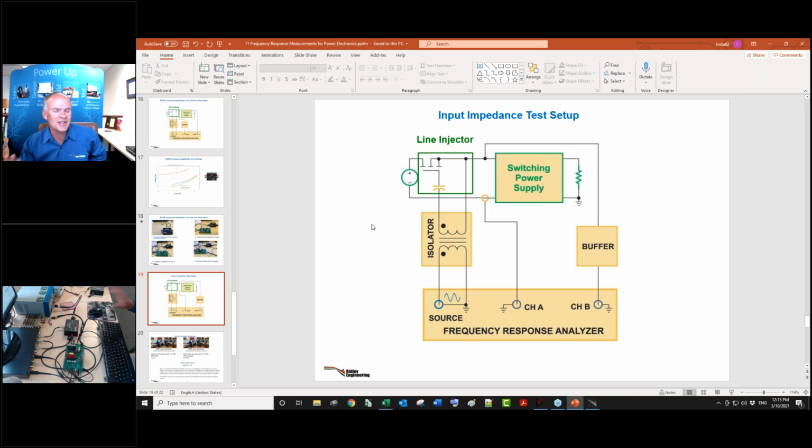If you can't measure stuff in the lab, measure it in LTspice. But find a way to go in the lab, get a signal generator, get a scope that can measure this, and look at these quantities, okay? And the big deal, of course, about a frequency response analyzer is if you're just using a scope, you've got all the noise. And you can't get rid of the noise easily and see the signal. Okay, so that's what a frequency response analyzer will do for you.